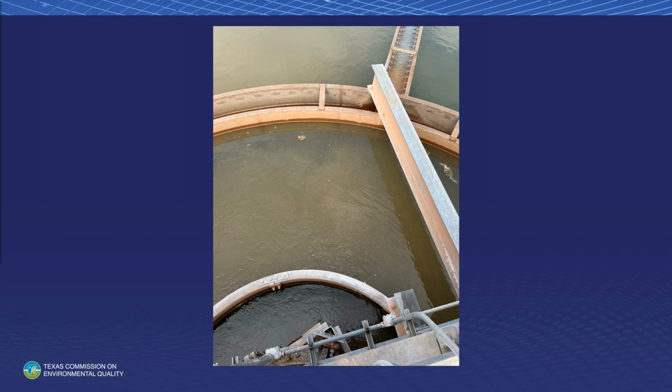With that polyphosphate, when it hits your customer's hot water heater, at about 140 degrees, it's gone, and all of your problems with your scaling ends up inside their hot water heater, and they get to replace the cost of all of that rather than you in your distribution system. So there are some issues when you talk about mud balls. Let's see if we can find some mud balls.